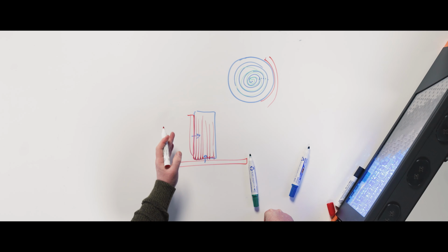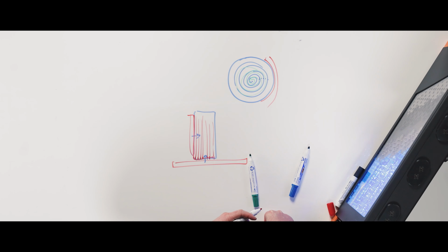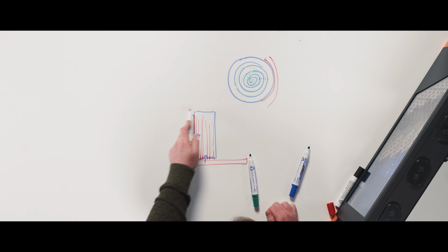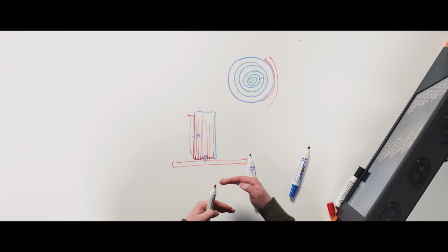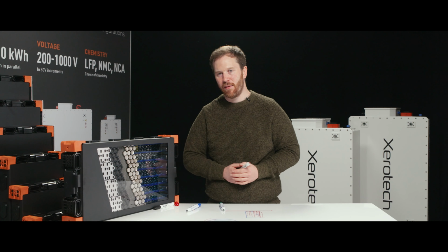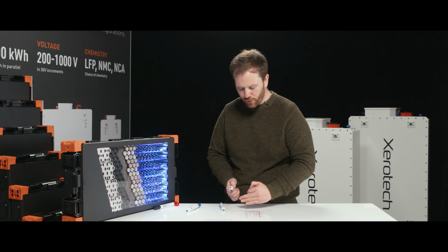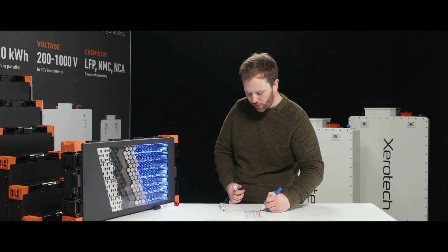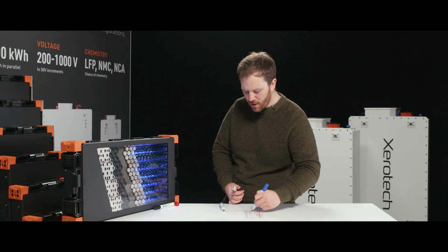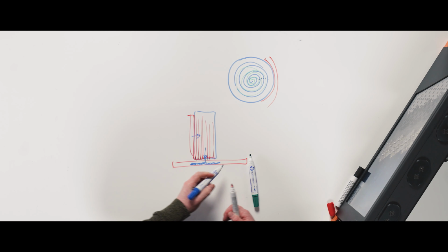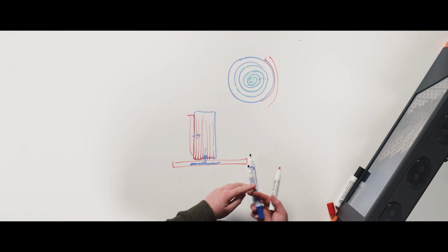So sidewall cooling tends to dominate higher heat transfer overall. It can in some cases lead to temperature gradients across the cell as you start to get to higher and higher levels of heat dissipation or heat exchange being required. So if you're cooling down here with something very cold, it's not able to conduct the heat down here very well. But it's even worse in a sidewall situation.